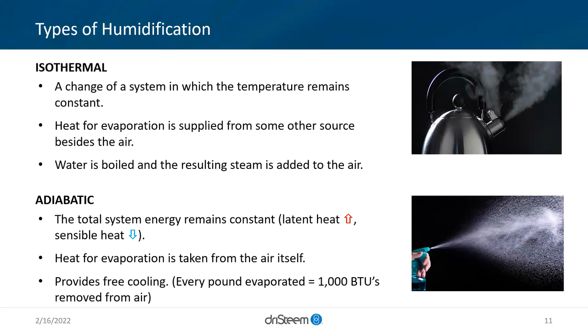Instead of boiling the water, if it's high pressure atomization, we're going to distribute this into a readily absorbed liquid aerosol, essentially, and have that air meet the contact with the water and evaporate. Wetted media, evaporative media solutions will have a surface, the media surface, that will allow that heat transfer to take place. Ultrasonic is another technology in this space for adiabatic, where it's creating a really fine mist or fog that will use that energy in the air.